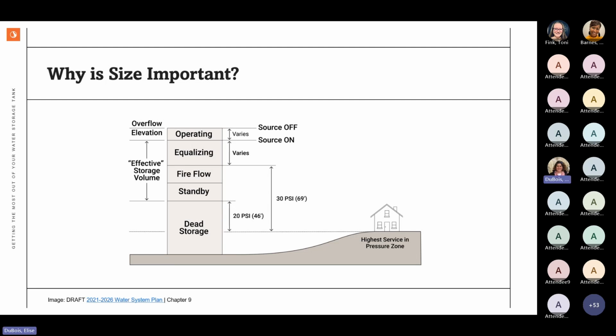After that, we really look at some of the other mixers out there. They're less frequent, less in use. I've heard people ask me to look at draft tubes, not understanding that a draft tube or the pipe and valve system, those are really passive mixers. So if you don't meet the requirements for a passive mixer, we're not going to look at those. The draft tubes were the standard 20 years ago. They're still kind of the primary standard for elevated tanks. We still do put active mixers in elevated tanks. You're not stuck with it.